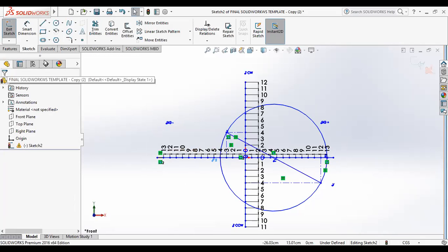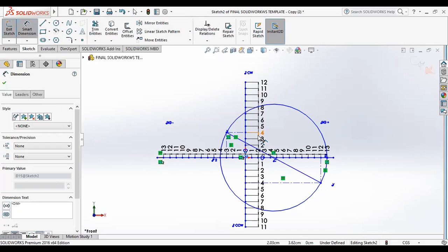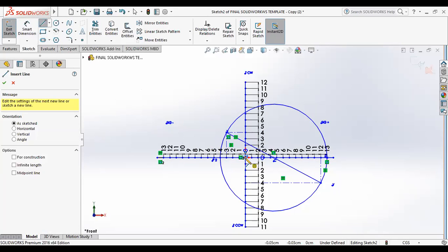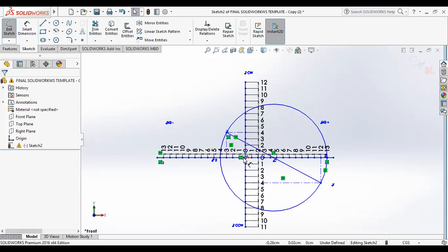Now from the origin to this point is my sigma 1. Draw a line if you want. You can calculate, you can just count. See, this is around 130 MPa. I can write sigma P1 equal to 130 MPa. Isn't it 130, 132 MPa around this point? If you can, draw a straight line to measure. Since you can measure in the graph sheet, you can directly measure.